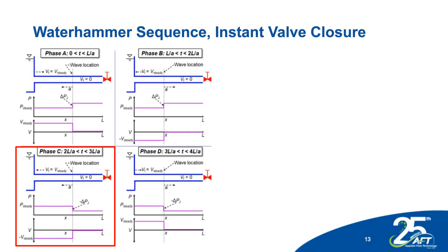pressure rise. This can cause problems in a lot of systems because if that pressure reaches the vapor pressure of your liquid, you can start causing cavitation and flashing of your liquid, which can cause all kinds of problems in operation and other secondary pressure spikes that are even larger. So that's something that you would really be advised to avoid.